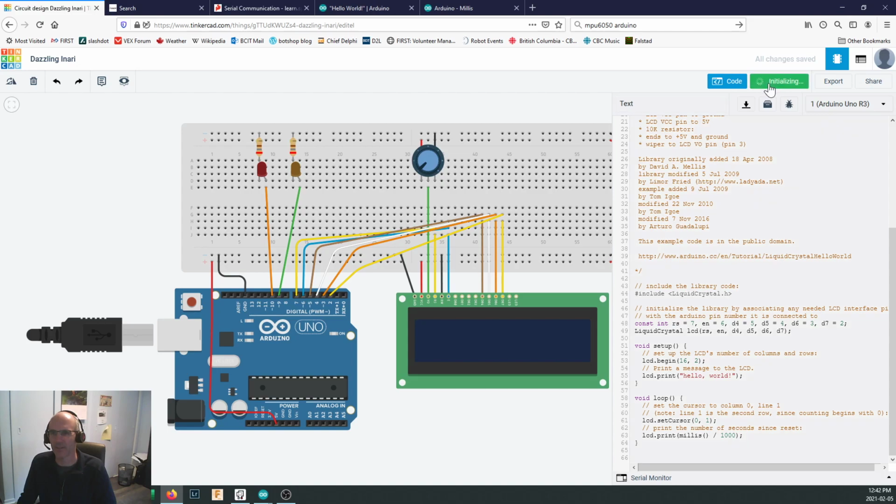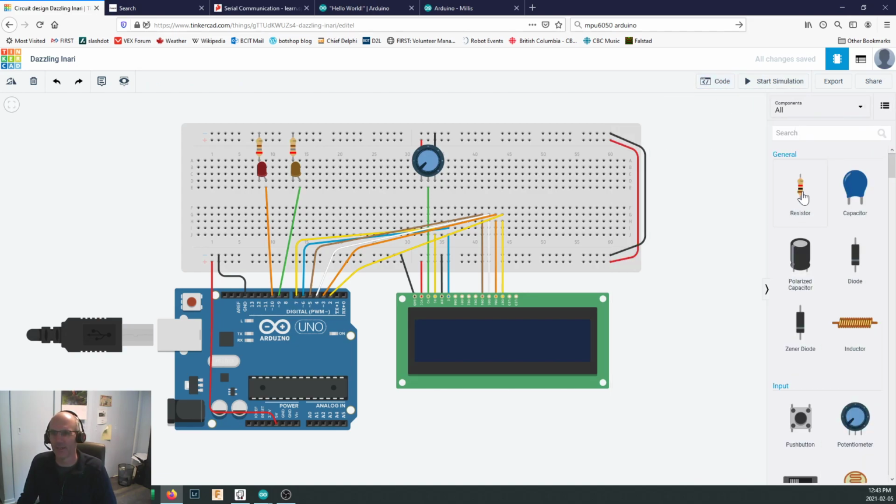So let's just start the simulation and see what it does. And like I said, I wasn't sure on this one if we needed to hook up an LED on there or not. So let's just stop that simulation. It looks like we do. Okay, move your code out of the way right on here and just add a resistor from your positive.